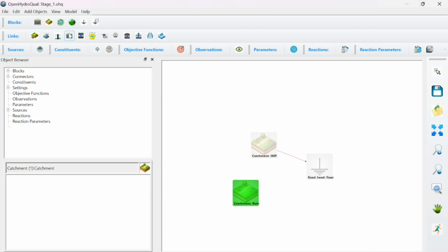And then we got some links as well. You can have a drain pipe, for example, situation. We have aggregate layer to soil zone. Now we're going to take care of soil later on, so we'll see how we use that one. And then there's a surface water to aggregate layer link. There's a soil to aggregate layer link.